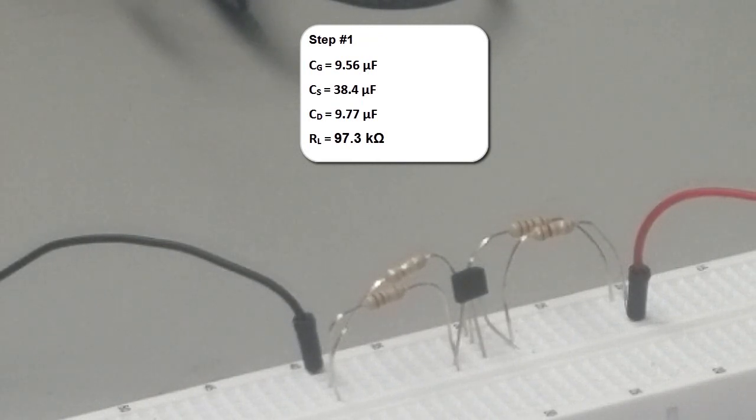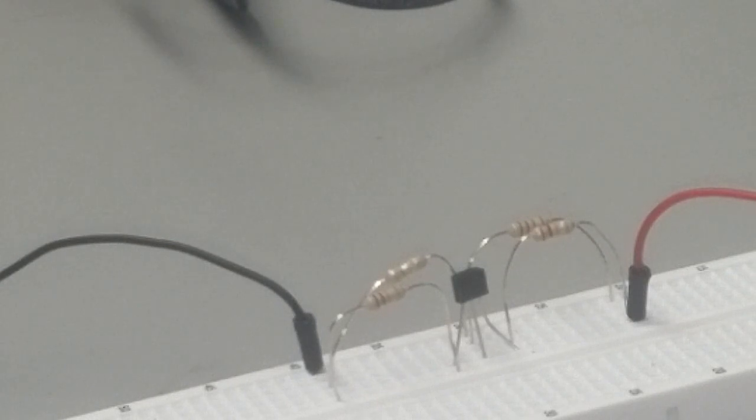So the first step is to measure the component values. The second step is to measure the DC circuit. So to measure the DC circuit, I'm going to remove the capacitances. So none of the capacitances is connected to the circuit. All the capacitances are removed. I only have those 4 resistors, R1, R2, RD, and RS, which is what we call the voltage divider circuit. So what we're going to do next is apply the DC voltage source, and then start measuring the voltages at the 3 nodes of the circuit. So let's do that.